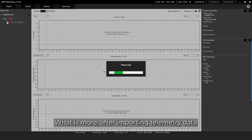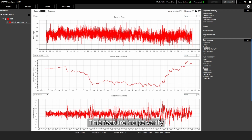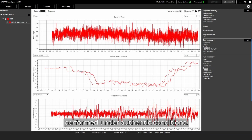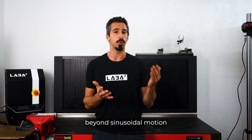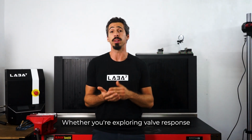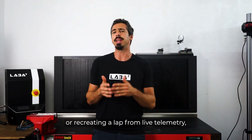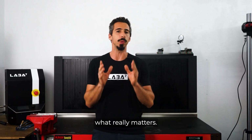What is more, after importing telemetry data and executing a test, you can compare the original motion curve to the actual result. This feature helps verify how closely the EMA followed the real-world input, and it gives you a clearer picture of how the damper performed under authentic conditions. These advanced profiles let you move beyond sinusoidal motion and start replicating real-world conditions. Whether you're exploring valve response with a chirp test, simulating terrain with pink noise, or recreating a lap from live telemetry, the Laba 7 software gives you the tools to test what really matters.